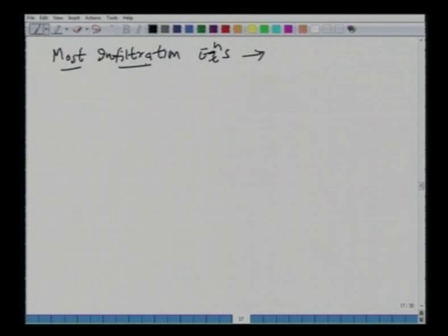Some of you may know this, but all these infiltration equations give us the potential infiltration, that is, under any given climatic and catchment conditions, the maximum amount of infiltration that can occur at that given point of time. That is what any equation gives us. Then the question that arises is, how do we find the actual infiltration? For example, Horton's equation gives you a certain rate, f is equal to 2.37, but it is not actual, it is potential.